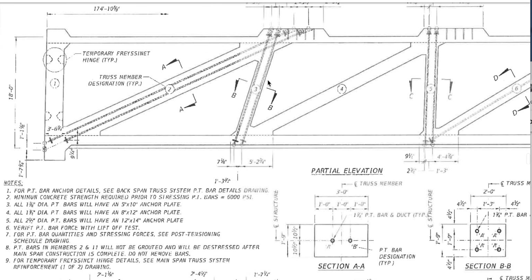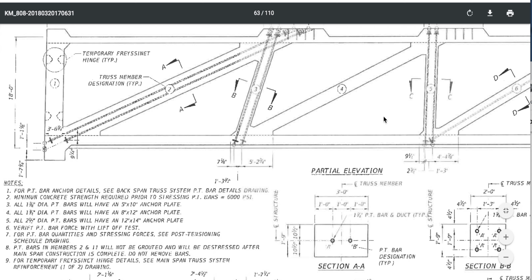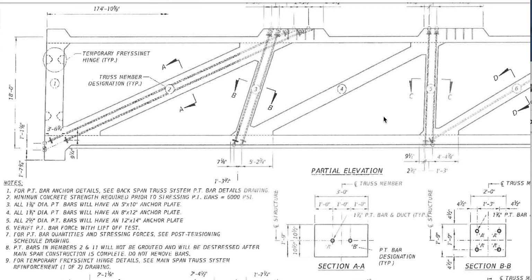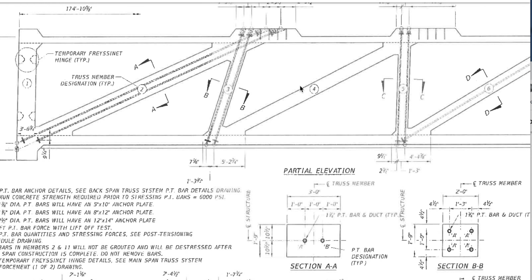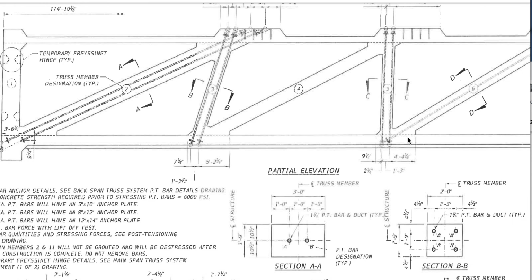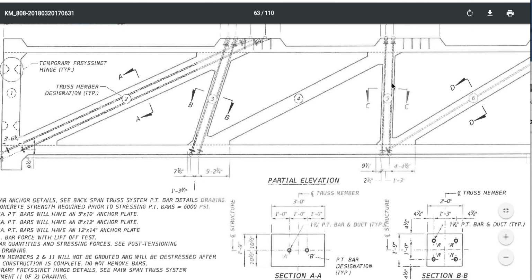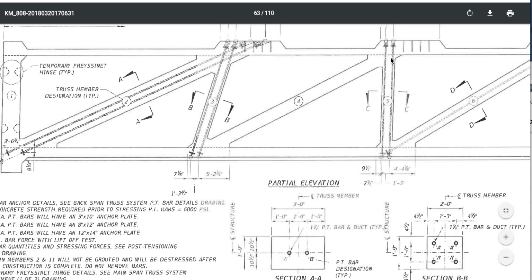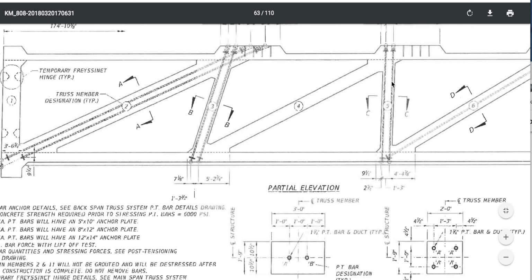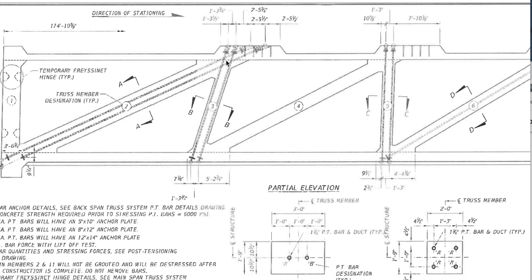Of course, it identifies itself if you can see the deflection. It's up to you now to extrapolate what the deflections are doing on each joint. And this is all we're looking at now. The sagging is not just a freebie. In an interlock system like this, you can't have sagging. You're going to have shear moments and things like that. If you have sagging, this sags down. The concrete here will now start acting like a load on all these bars, like a lateral load on the bars. How much did you calculate that shear reaction on the bars?